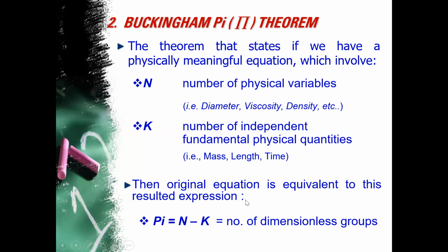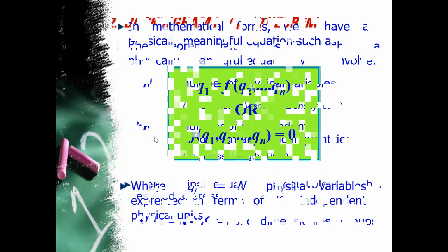Dimensionless group, which is the pi, only one, right? Okay, but this time, because the number of variables is increasing, we use this one to actually identify the total number of dimensional groups. So basically, there will be several pi: pi 1, pi 2, pi 3, and so on. All right, so the number of pi groups will be equal to this n minus the k. Okay, right? So don't worry, we'll look at an example.